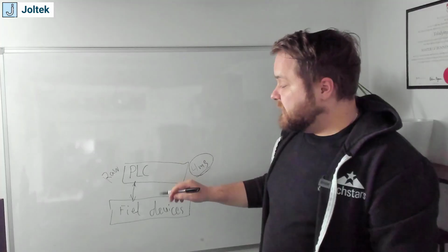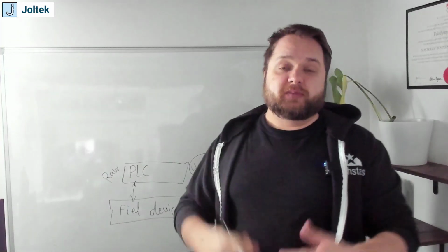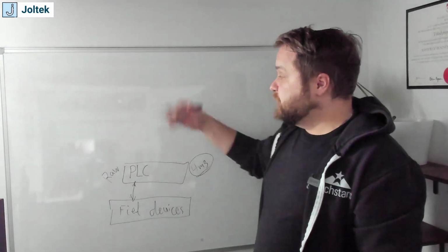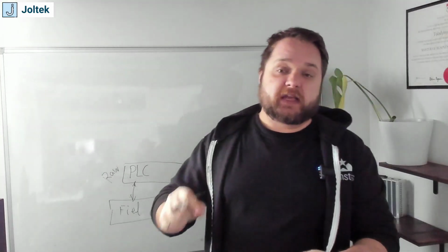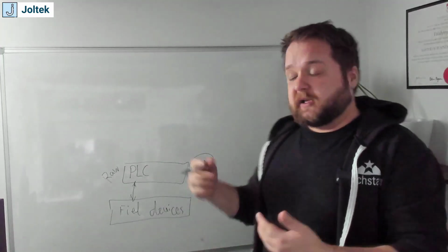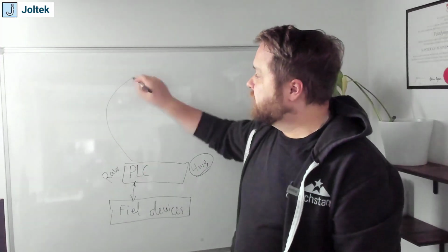Then the PLC is going to be polled, or essentially be asked for that data to be sent to the next layer. Like I said, it doesn't necessarily mean that the data needs to go through SCADA in order to reach MES or ERP. It can be going directly all the way to the ERP side.